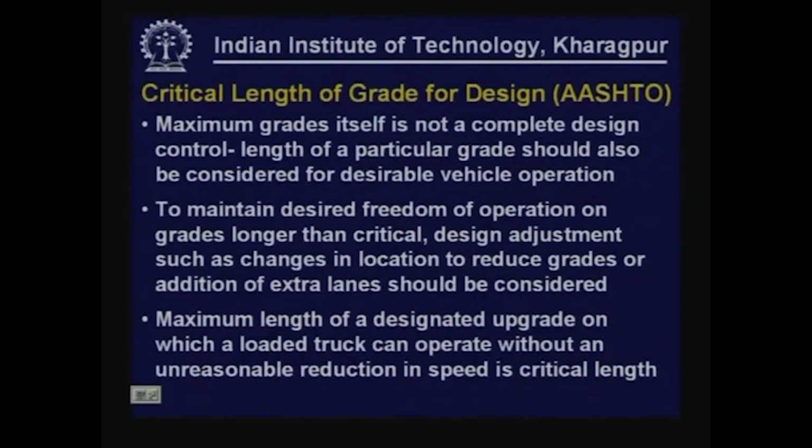Coming to the critical length of grade for design. Now, we have talked about the maximum grade, but maximum grade itself is not a complete design control. Length of a particular grade should also be considered for desirable vehicle operation. This is purely based on the fact that as the length is more and as the grade is also more, there is a reduction in speed. We have already seen the trend earlier.